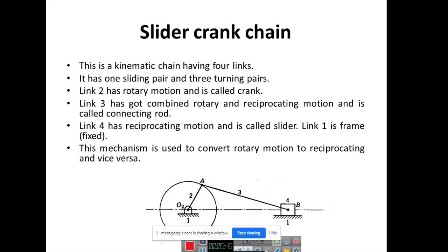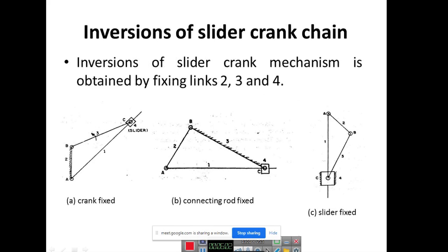So the best example is your engine: piston, crank, and connecting rod. The crank is going to rotate, and the connecting rod is going to push the piston. The piston is nothing but the slider, so that will reciprocate. So this is the slider crank mechanism.